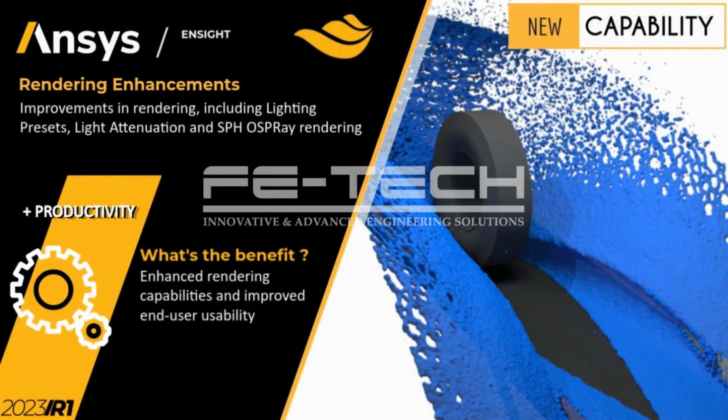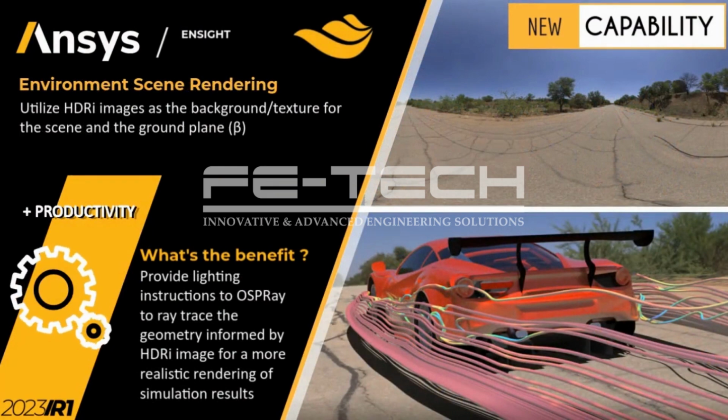The rendering improvements, including lighting presets, light attenuation, and SPH Osprey rendering, increase the end-user productivity and usability when using ANSYS EnSight. And the Osprey engine can now get lighting instructions to ray trace the geometry from HDRI images for a more realistic rendering of simulation results.